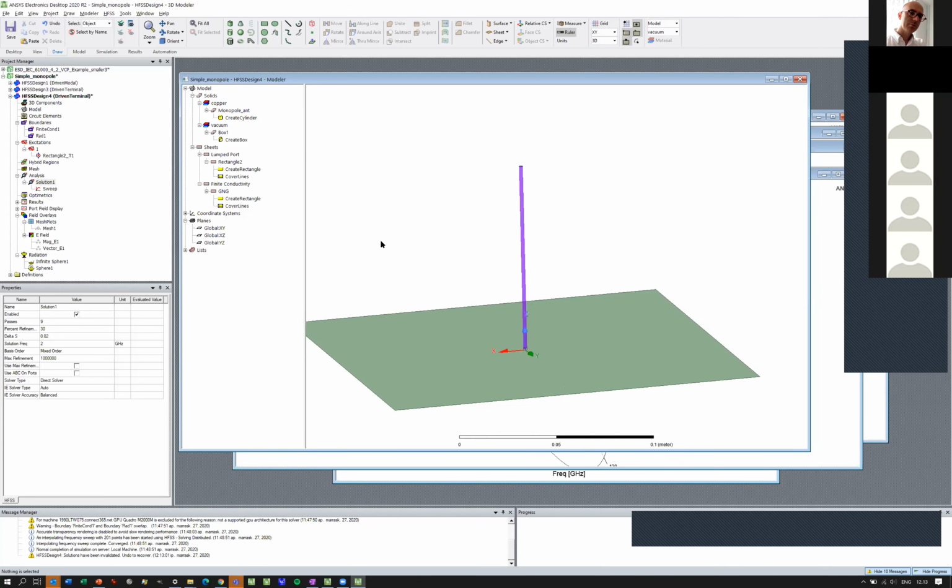Derivative means that I will restore the design. That means that now I'm playing a little bit with the height variable, even though I'm not recalculating all the different height values. It's approximating how results will change if the length of my monopole antenna changes.